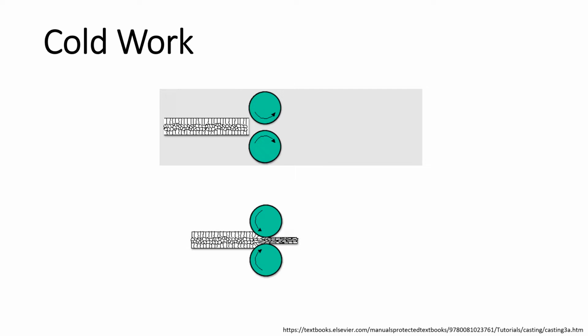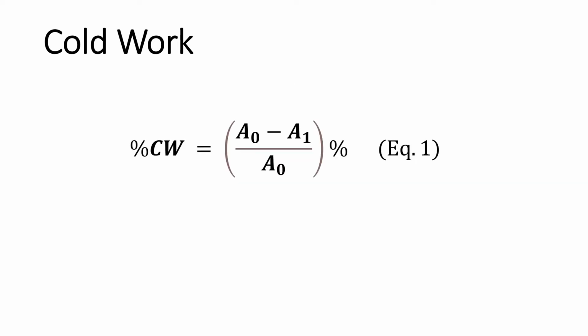When the material gets cold worked, new dislocations form and the average distance between the dislocations decreases. On average, the interaction forces between the dislocations are repulsive. More dislocations tend to hinder the motion of a dislocation by the other dislocations, making the resistance to dislocation motion more pronounced. As a result, the higher defect density causes the material to require more stress to deform.